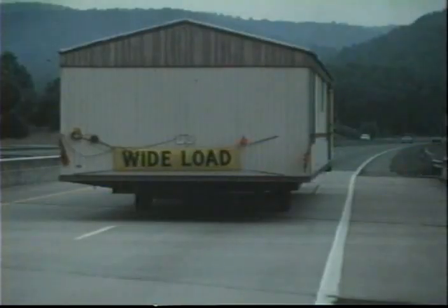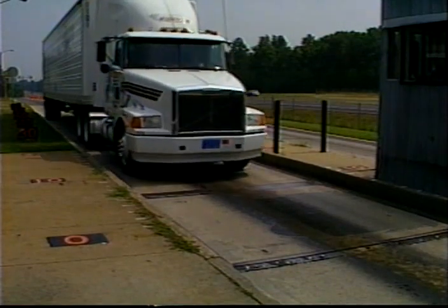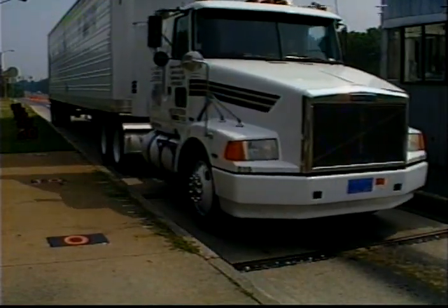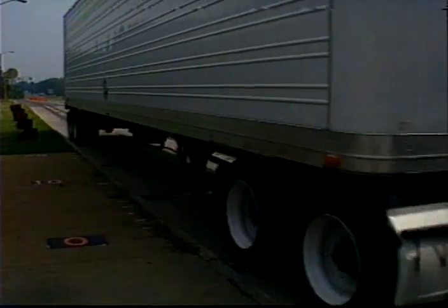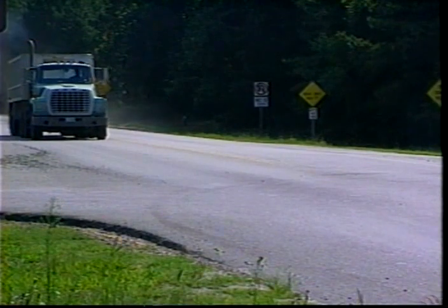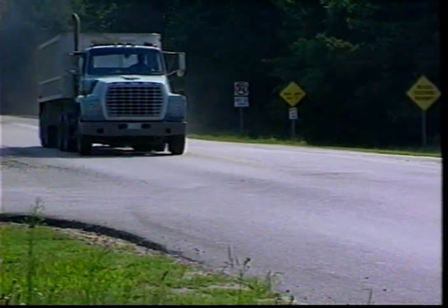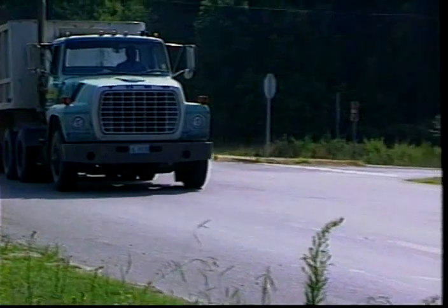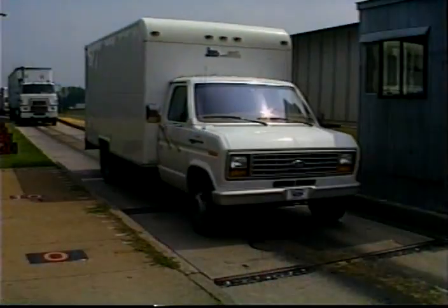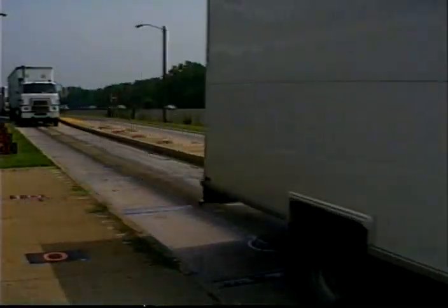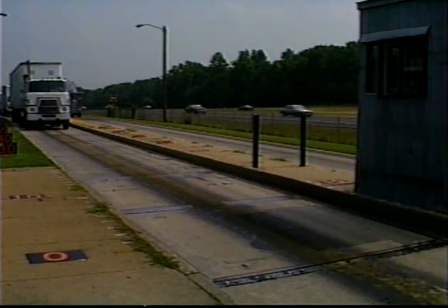Oversized loads are loads that are over length, over height, over width, or any combination of the three. An overweight vehicle is one that is over the gross legal weight limit or over the weight allowed for a specific axle. For oversized or overweight vehicles, specific routes appropriate to the over limit are designated. Overweight vehicles are routed to bridges with extra capacity or to bridges that can carry the load by limiting other simultaneous loads or by temporarily reducing the factor of safety. The number of repetitions of increased stress range is controlled to prevent fatigue damage.